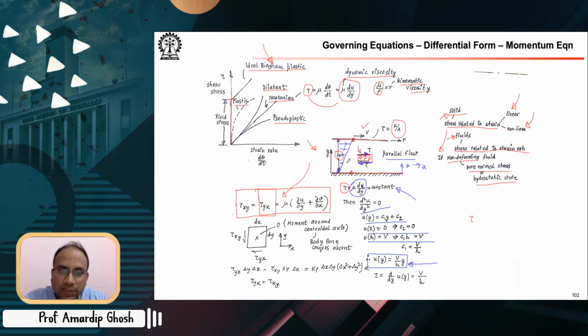So that is a viscous fluid between two parallel plates. The top plate starts tugging along. The top layer of liquid flows because of the no-slip condition, cohesion, and other things. The top surface moves with the velocity of the plate, and this top layer of fluid keeps pulling the lower layers from left to right, and eventually you have a profile given by this constant velocity gradient. We are yet to prove this particular aspect.